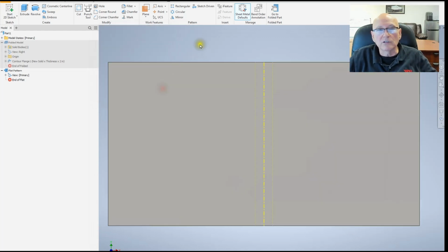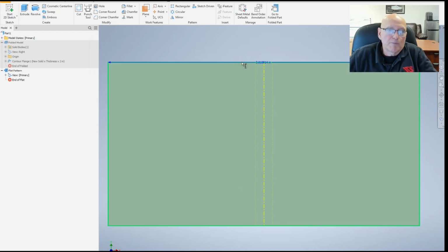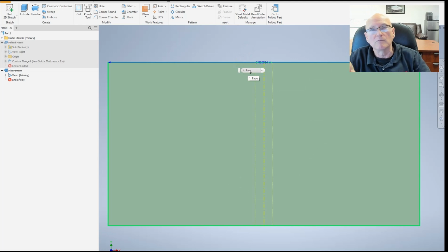And we're going to cancel it. Let's measure it again. It should be 3.801? No. So it changed about 11 thousandths of an inch, 3.8108. So it doesn't have that pronounced effect. But remember, we're dealing with a piece of metal that's only 1/10 of an inch thick.